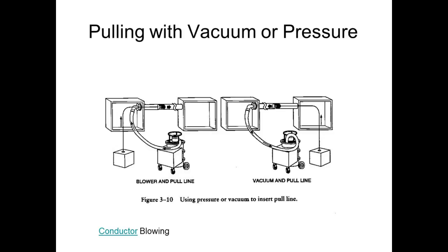So what they'll do is they'll put a length out there, and they'll hook it up to that conduit and pull their string through there. And either the string is going to be big enough to make your pull, but if it's not, you shoot a small string through there, and then you use that to pull a rope through there, and then hook your cable up to that.